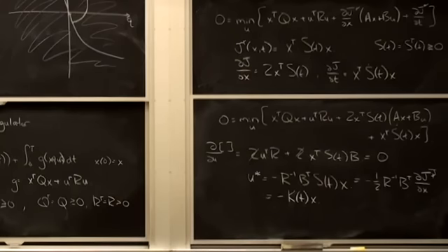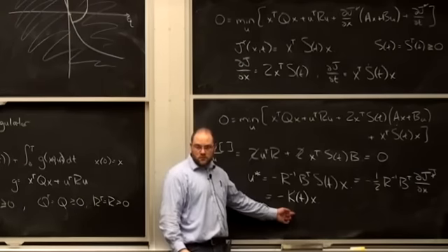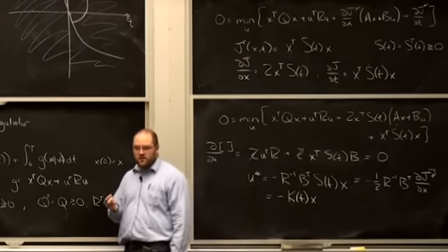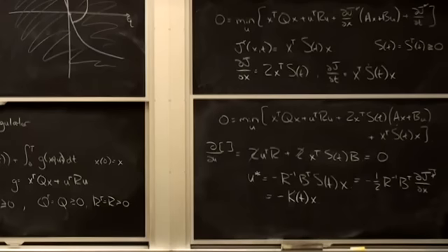Yeah. So intuitively, why should I take a different linear control action if I'm at time 1 versus time 2? Because you're time limited, so if you're very close to the final time, you want to use lots of control because you don't have much time to wait. Awesome. Yep. This is a quirk of having a finite horizon cost function. In the infinite horizon case, it turns out you're going to just get u equals negative k x, where k is invariant of time. But in the finite horizon problem, there's this quirk, which is the time ends at some point, and I have to deal with it, right?